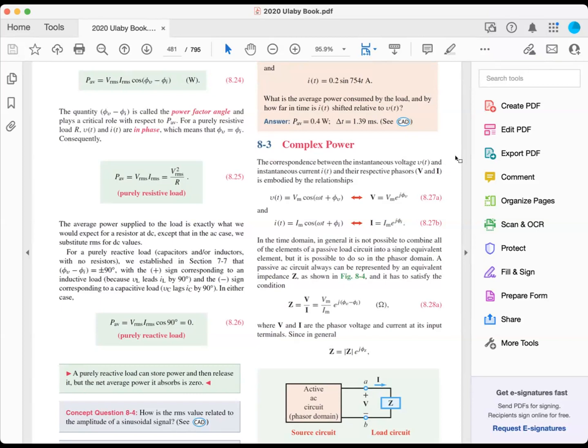Okay, like Laplace. Yep. So same idea with the complex power: we are now having AC power, and to manipulate it, we want to move to the S domain. And in the S domain, we've just defined these terms and they don't necessarily tangibly mean anything. So what means anything is that power factor. The power factor gives us a number in the end, like 0.5 or 0.8. What that means is now we can use that to compare different systems and say it has this power factor, and that power factor means something.